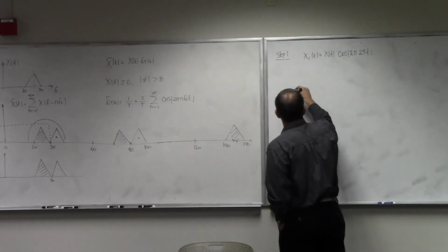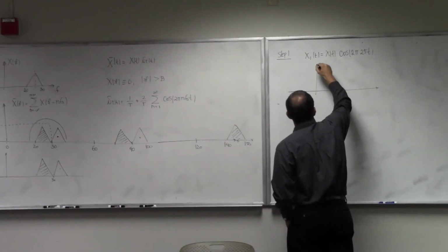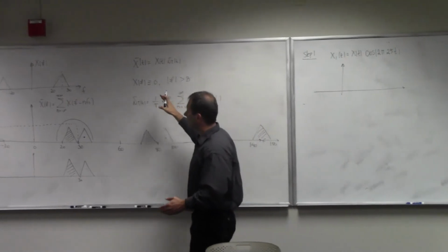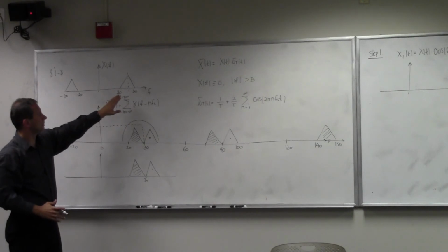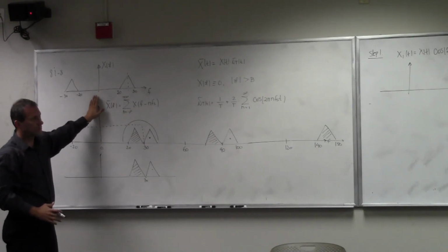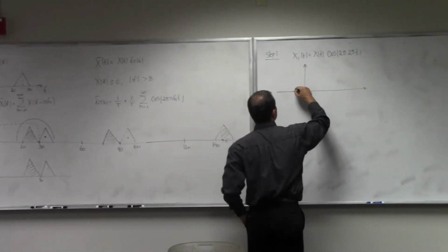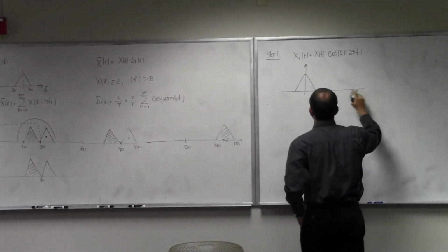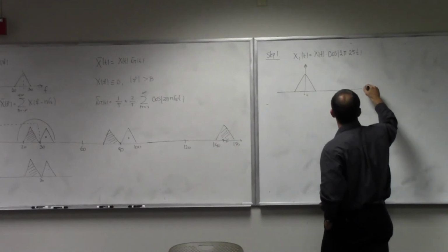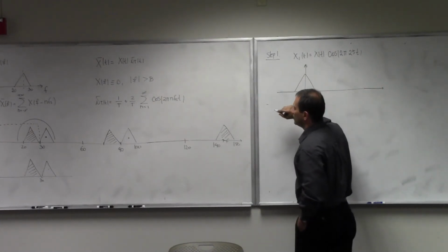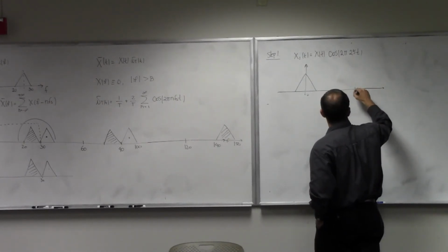What will this do? This will take the spectrum of this signal and translate it, using the modulation property, to the sum and the difference, right? So you're going to get a replica of this signal. You're going to get one that will be centered at 0, and the other one that will be centered at twice the carrier frequency. So it's going to be centered at 50, sorry.